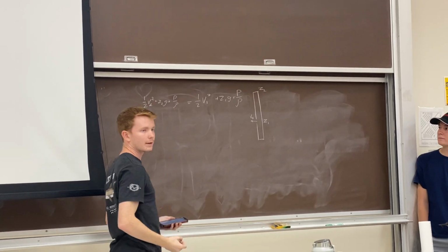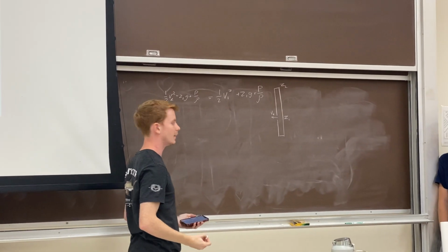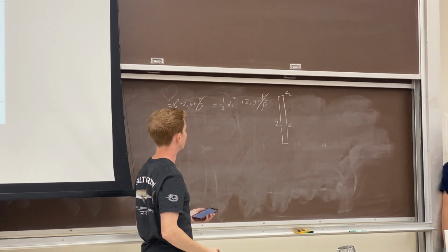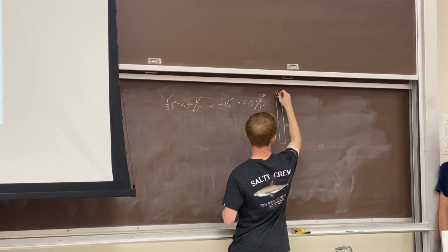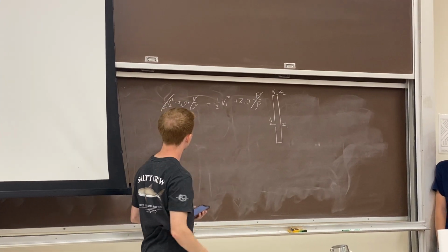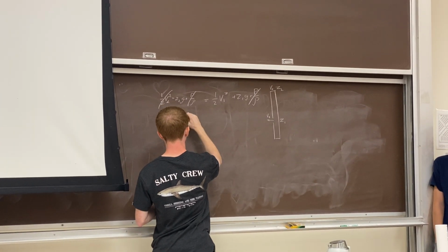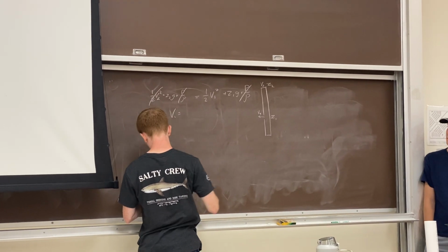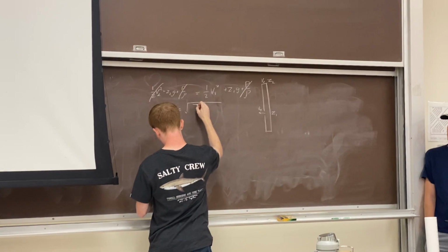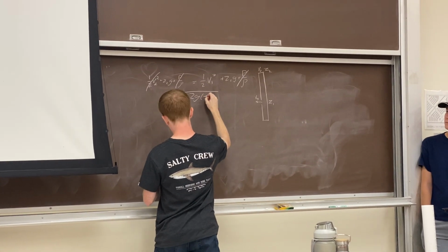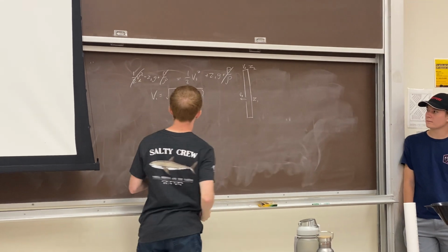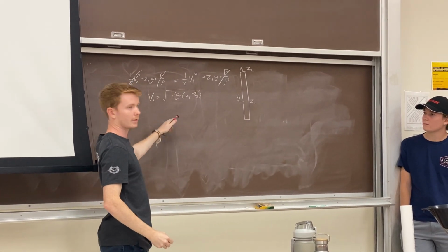Now, of course, density and pressure will be the same. You can cross those out. This will be velocity 2. Velocity 2 is 0 because it's at rest, so cross that out. So v1 is going to end up being, when you do the algebra for all of that, the square root of 2g(z1 minus z2). Of course, right from the start, we can see it's not dependent on mass.